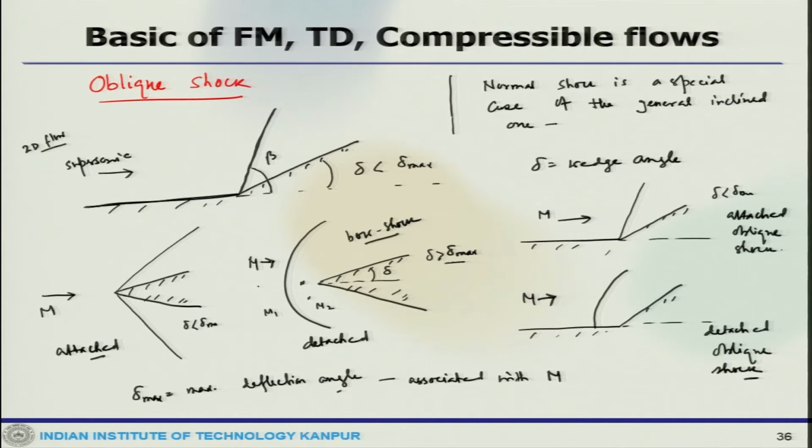Now, at the center of a bow shock, a normal shock also exists. When there is a bow shock, there could be a normal shock at the center with subsonic flow resulting. As the wave front curves around, the shock angle actually decreases continually, with a resultant decrease in the shock strength. So, with this the strength also decreases. Eventually, one reaches a point where supersonic flow exists after the shock front.